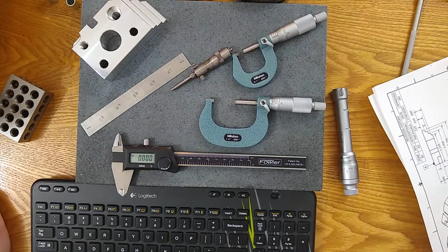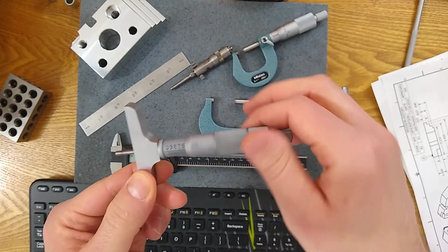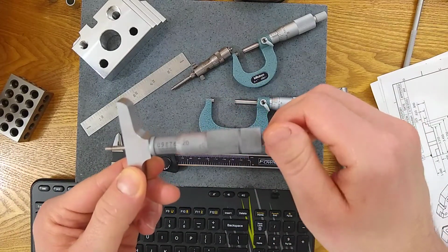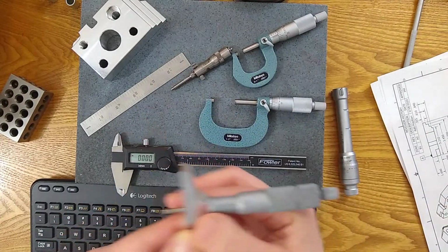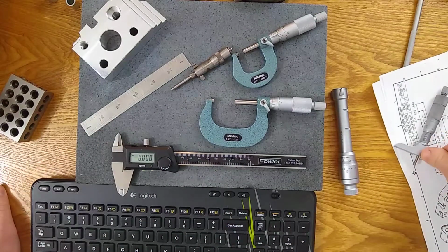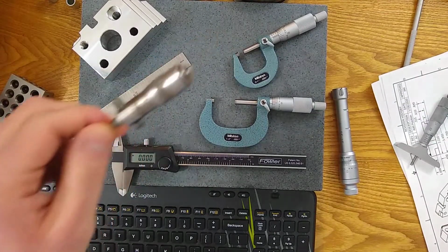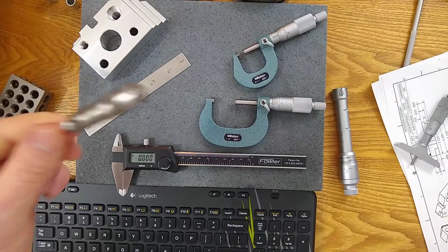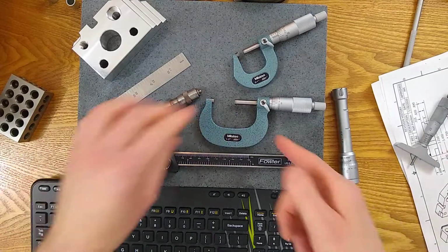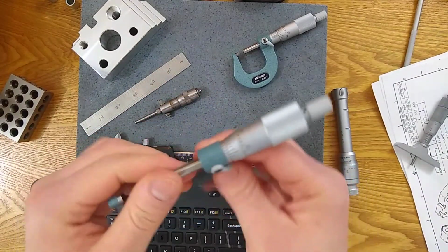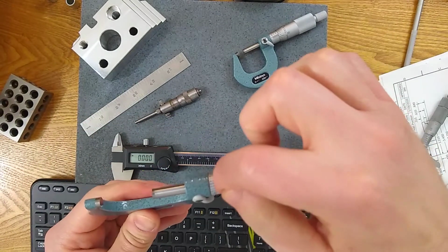Depth micrometers, resolution is actually only 1,000th in most cases. In most cases, these don't have that vernier scale accuracy on there to help you. So you're gonna have to kind of judge where that last digit lands, as I talked about in the video where I talked about vernier scale. ID micrometers, again, do not have resolution past 1,000th. And OD micrometers, the most accurate we've seen on the resolution anyway for micrometer, you get down to a 10,000th of an inch with the vernier scale here.